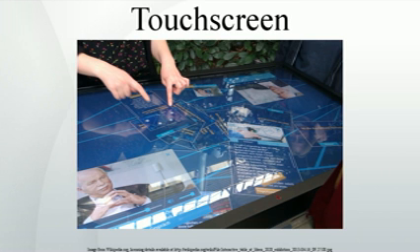Construction. There are several principal ways to build a touch screen. The key goals are to recognize one or more fingers touching a display, to interpret the command that this represents, and to communicate the command to the appropriate application. In the most popular techniques, the capacitive or resistive approach, there are typically 4 layers: top polyester coated with a transparent metallic conductive coating on the bottom, adhesive spacer, glass layer coated with a transparent metallic conductive coating on the top, adhesive layer on the back side of the glass for mounting. When a user touches the surface, the system records the change in the electrical current that flows through the display.